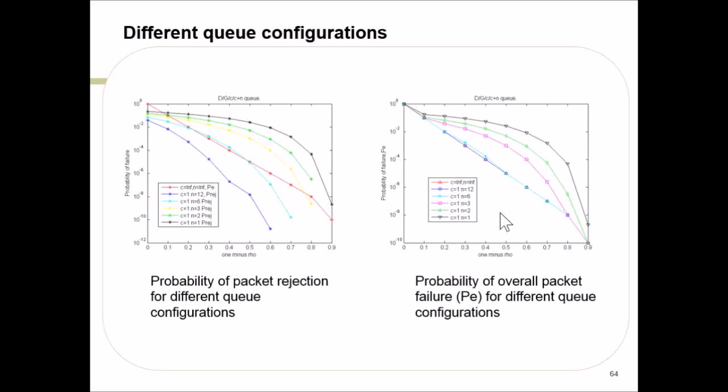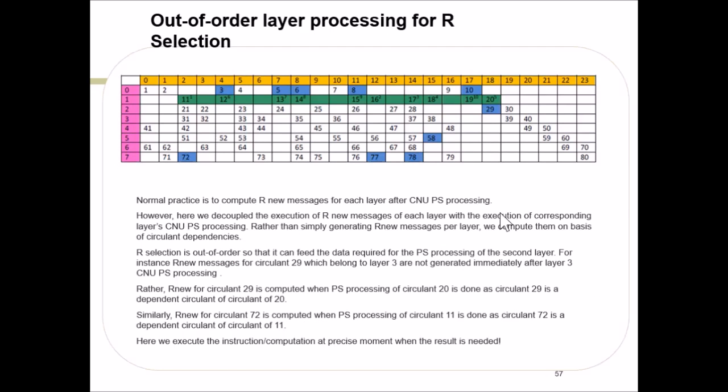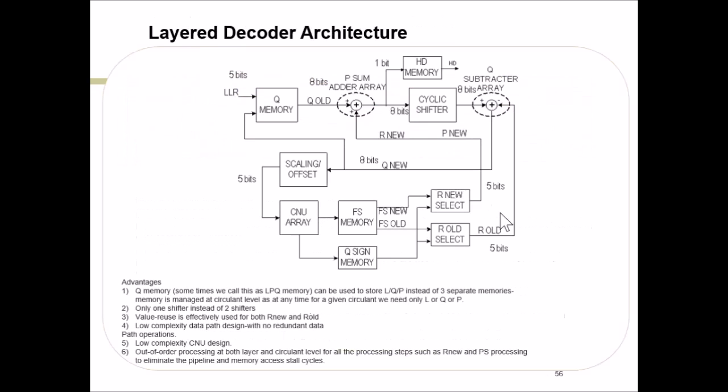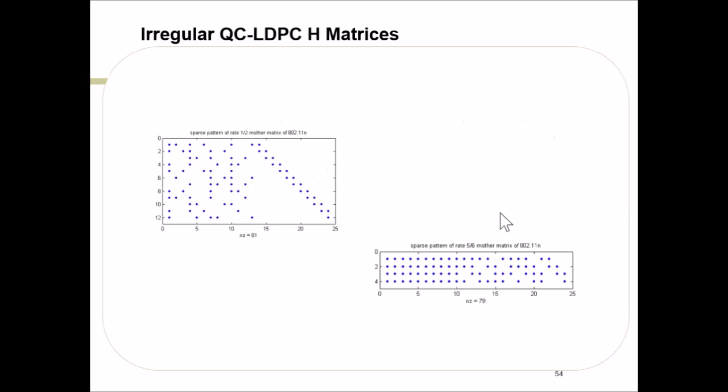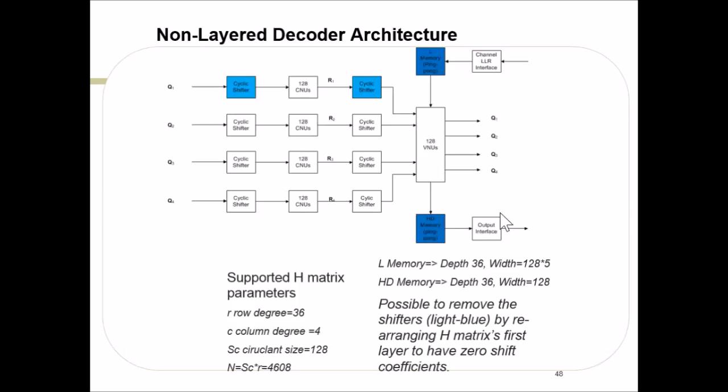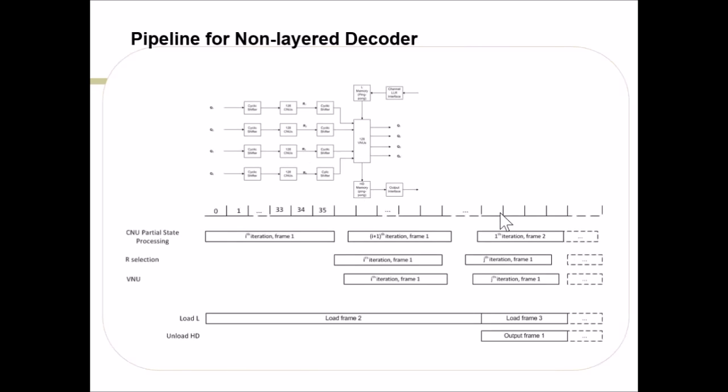But these are very short. It's a big packet, but it's made up of small codes, right? I thought it's 1,000. No, that H matrix represents 1,000 little teeny codes. This is a low density parity check code. It's like 1,000 small 8 to 10 to 16 bit parity codes, right?